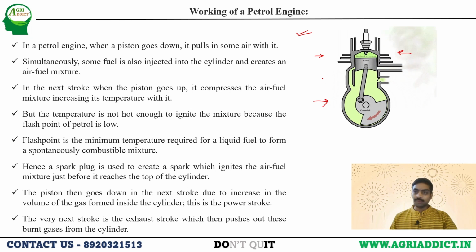Initially, the inlet valve will be opened so that the fresh air will enter, and again the fuel will be atomized and sprayed inside the cylinder. Once the piston moves up, what happens? The compression will take place of that particular air mixture, and the petrol will be mixed.